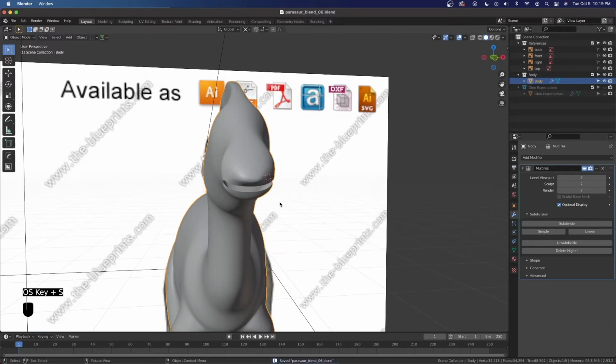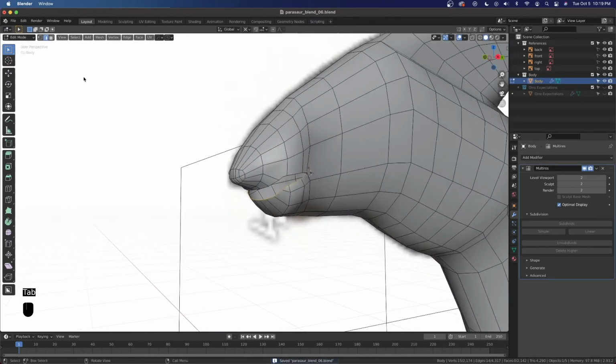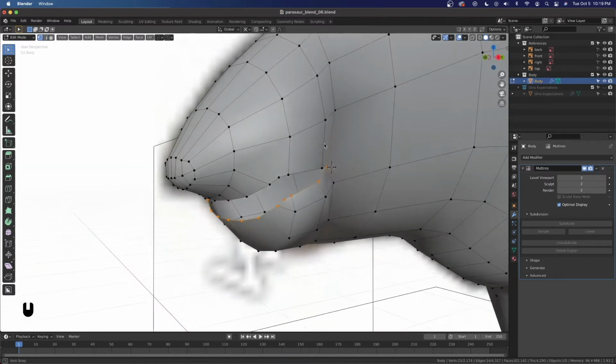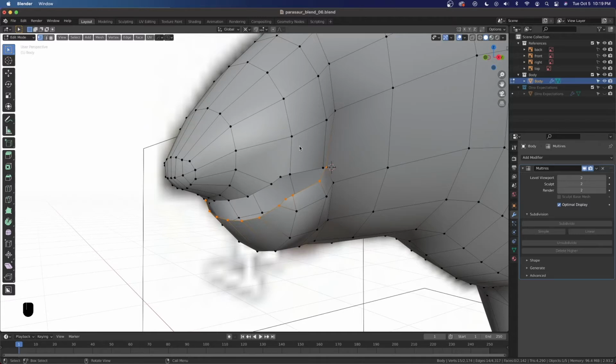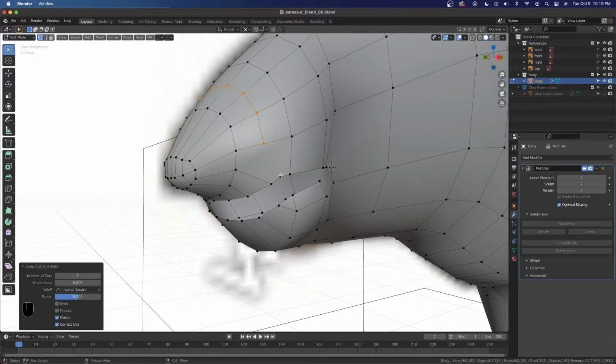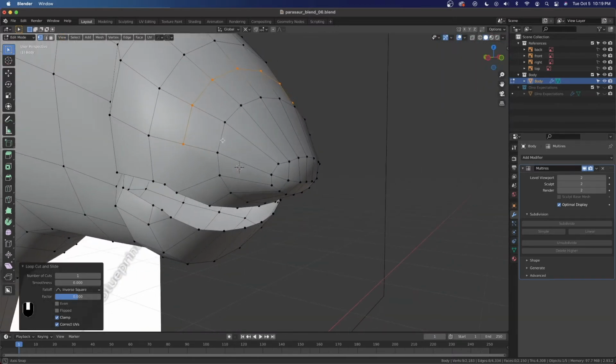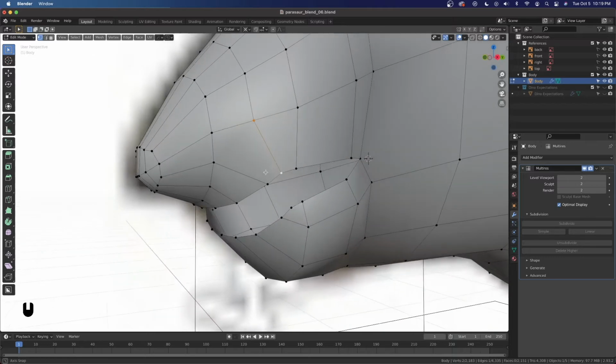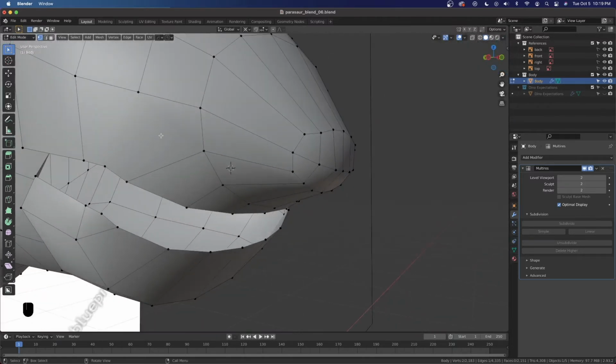So go ahead and save again. And let's make sure that our mesh is all quads. It looks pretty good, except right here. So what we want to do is Control R, and you could see the edge won't pass through because it has more than 4 verts. So we want to combine them here to make it 4. So we'll hit J to join. And now we've got 4. And I'm not going to bother to symmetrize because it's so simple, so I'm just going to hit J.